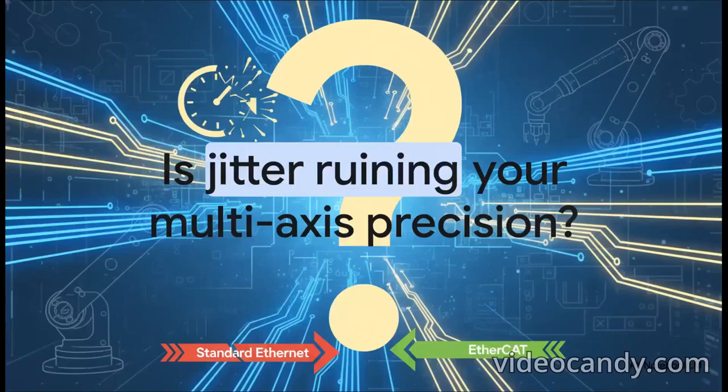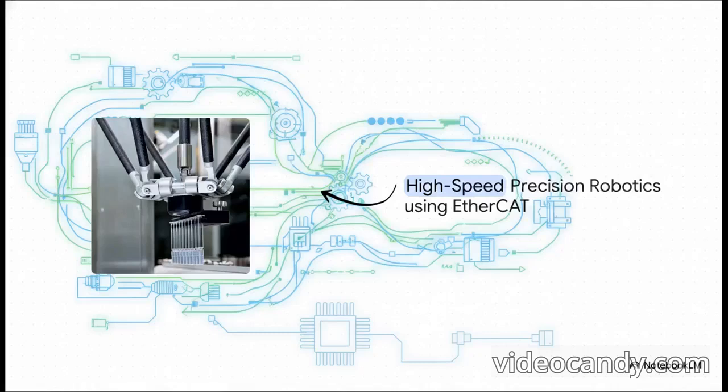If you've ever dealt with standard Ethernet and high-speed automation, you've probably hit that wall. Its fatal flaw: unpredictable latency. Standard Ethernet relies on collision detection and these really bulky TCP/IP protocol stacks, which basically means your messages can and will get delayed. And in a modern factory, that tiny delay is the difference between a perfectly machined part and a devastating hardware crash. Standard Ethernet simply fails when nanosecond-level synchronization is required. But today, we're setting up EtherCAT as the definitive solution to that exact problem.